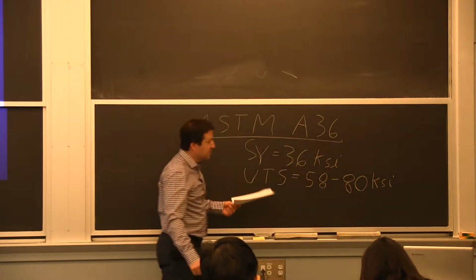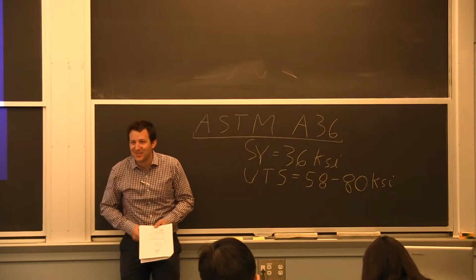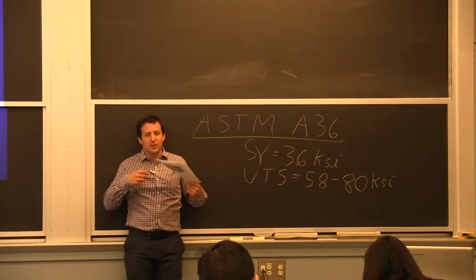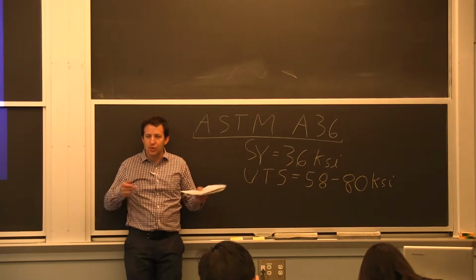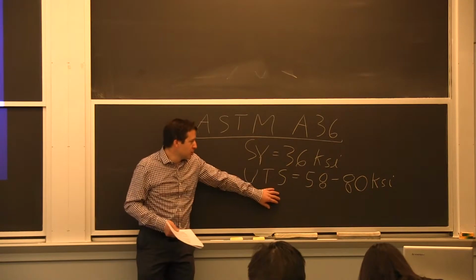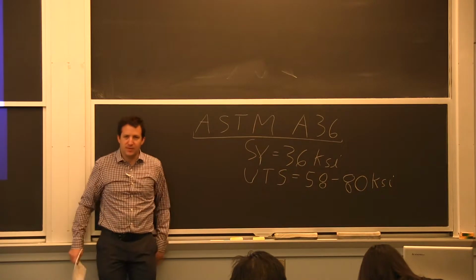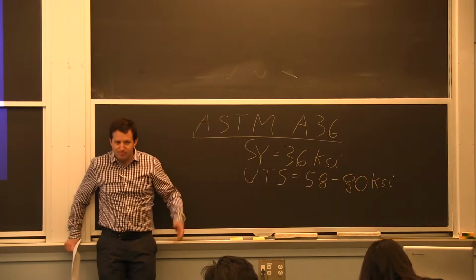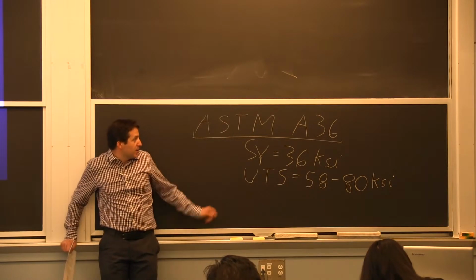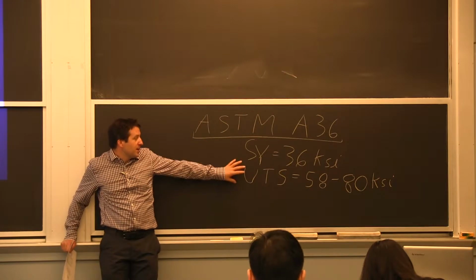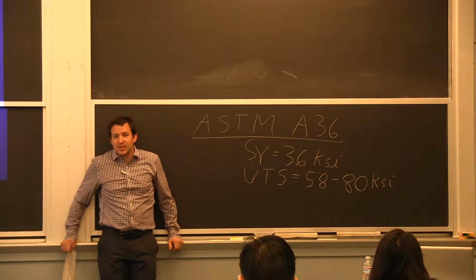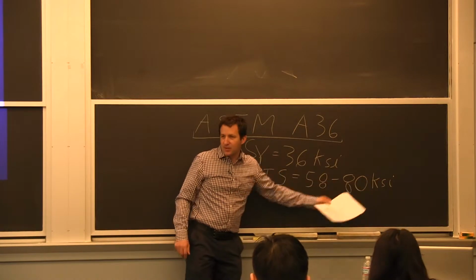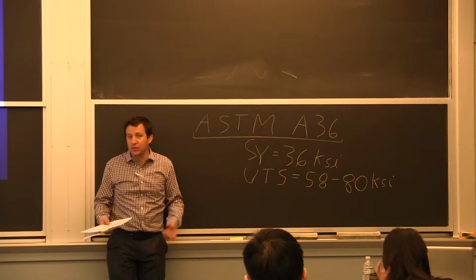If you ask me, that's a pretty broad range for today's standard. It's not that hard, through the selection of the grain size and the rolling process, to control your yield strength within about 5–10%. So when you see that range, it means a lot of the time the A36 steel will be a lot stronger than the minimum. But it can't be stronger than the maximum. There is a maximum there for you, and it could be to your advantage.